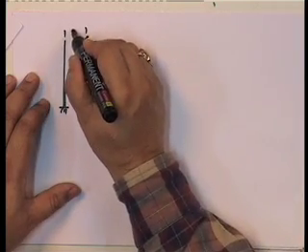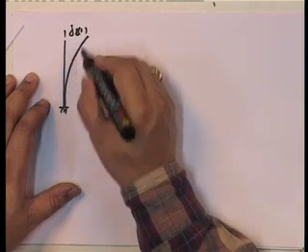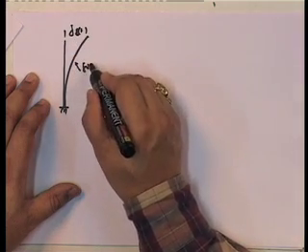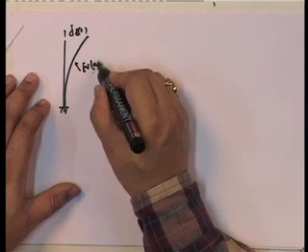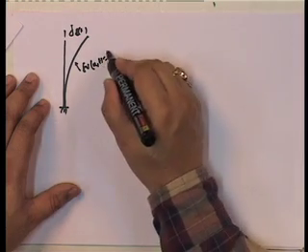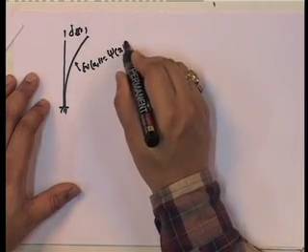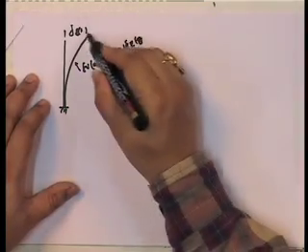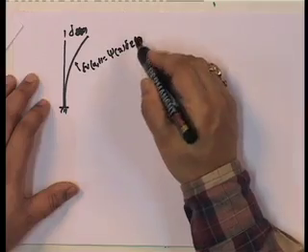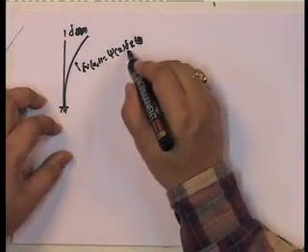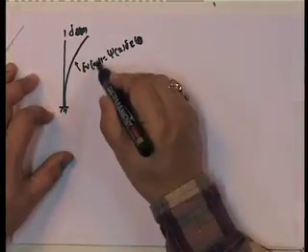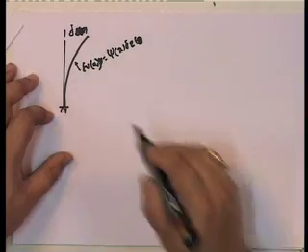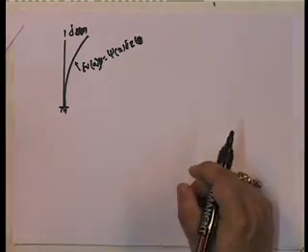So, del v x is equal to xi x into del z. Sorry, not del z of t, this is just del z. This is the virtual displacement, xi x into del z. This is only with x, because this is a virtual displacement.